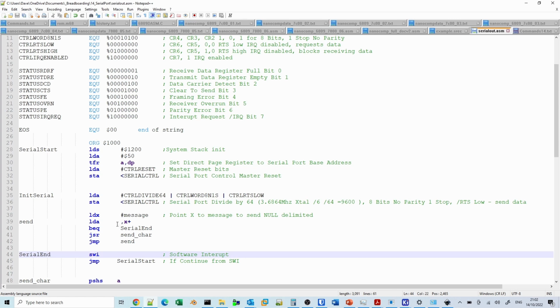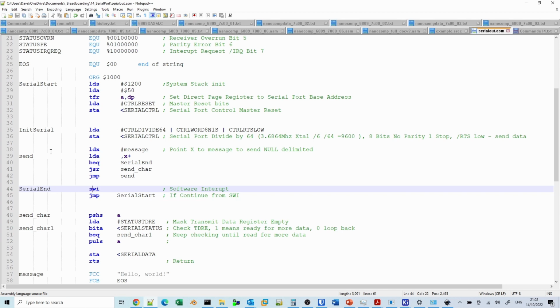The key thing we are going to have to do here is we don't have any way of loading software down onto the nanocomp at the moment until we finish this particular video. So what we're going to have to do is just look at the listing of this and type in the bytes manually. There's only about 30 or 40 bytes to type in, so it won't take very long. But once we've completed this work, we'll be able to download programs automatically from PC to the nanocomp.